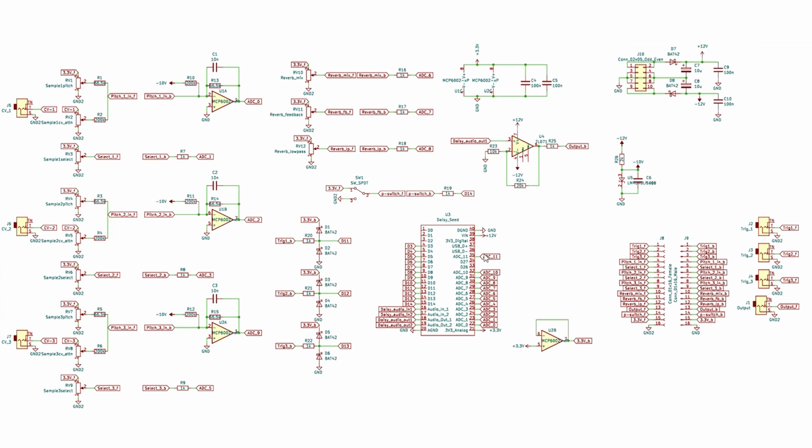Yeah, and there's also a reference voltage of -10 volts that's used to condition the signal, and I usually put Schottky diodes on the voltage input just so that if you put the connector the wrong way around, nothing happens.